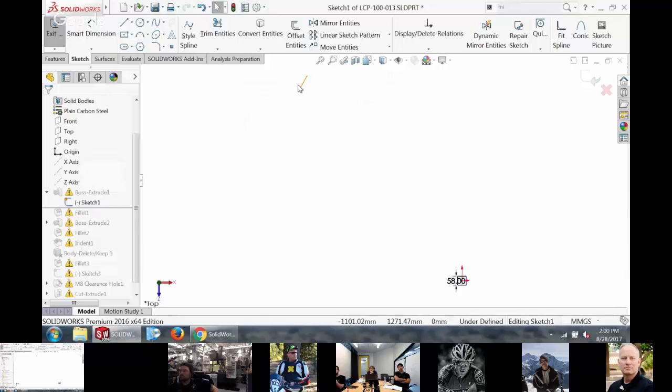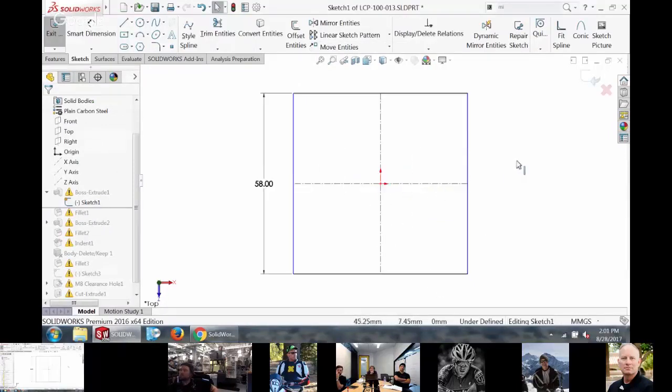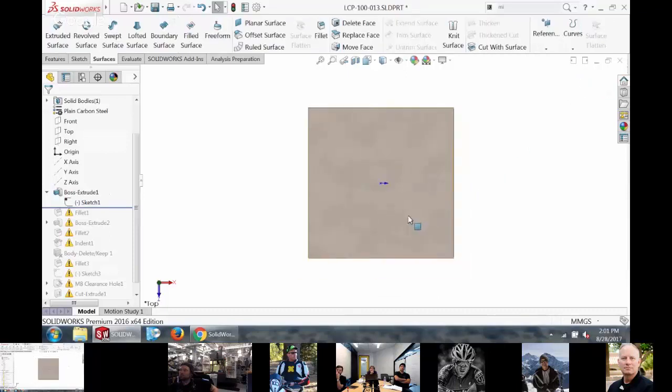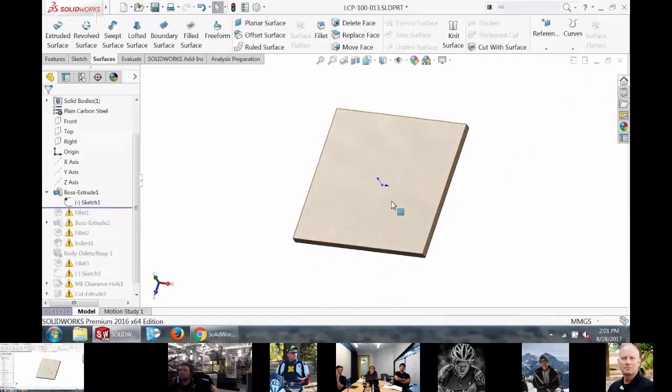This also might help when you're in an assembly and it seems like things aren't right. If you hit fit screen and everything gets really small, you probably got a part like half a kilometer away from another part, and that can jack up your screen. So that F sometimes can help us out. When I hit F now, you just zoom up. Let's exit out of it. And hey, what do you know? It built the first feature.